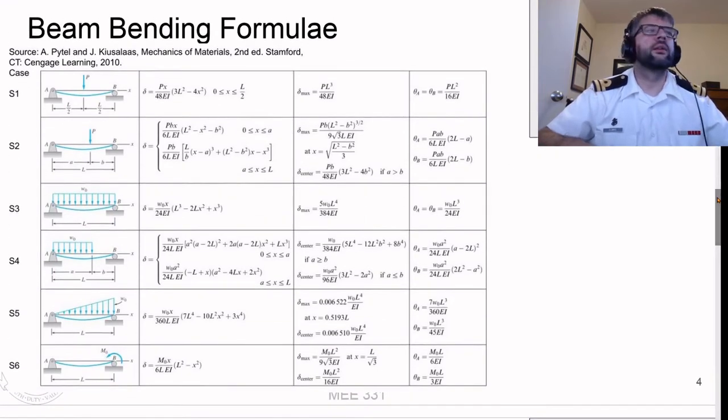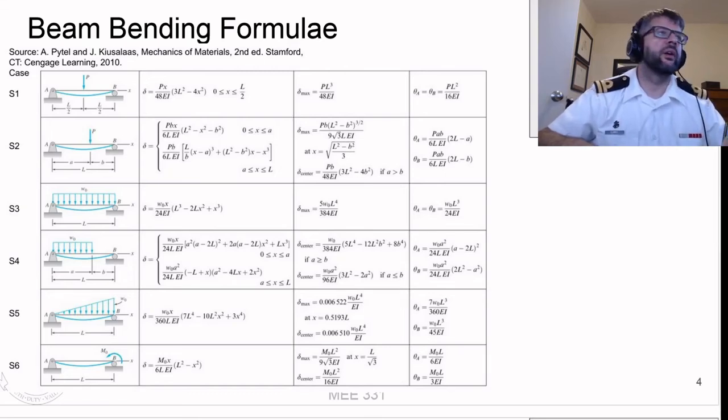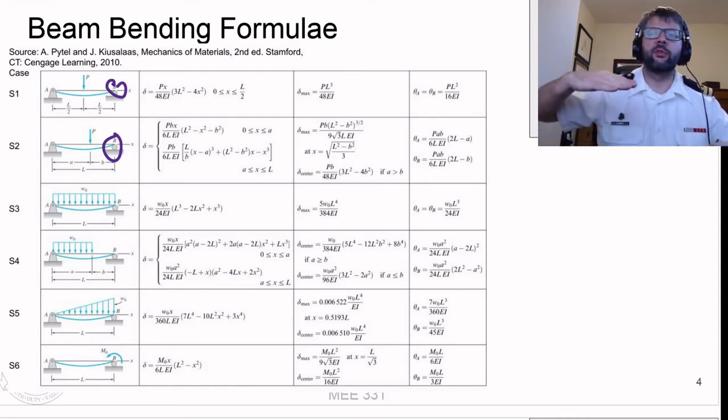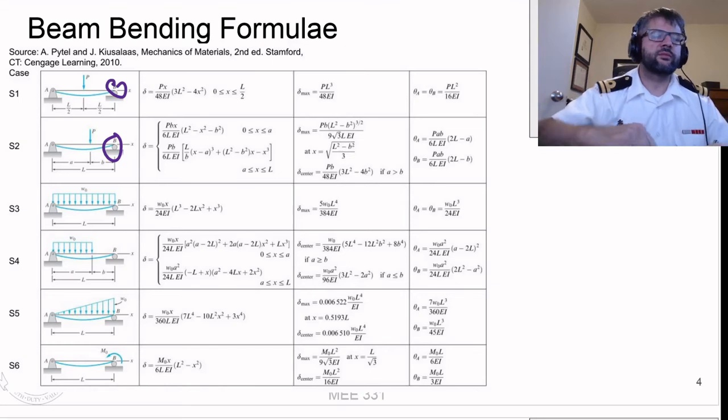So got that for cantilever beams. We got this also for simply supported beams, supported on both ends with a pin joint, except of course, conceptually speaking, they'd simplify it by treating the one end as a pinned roller, so it's able to move back and forth a little bit.